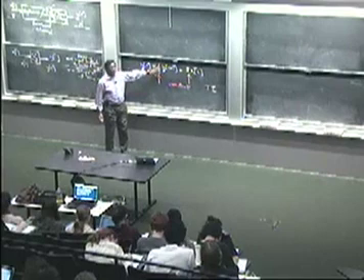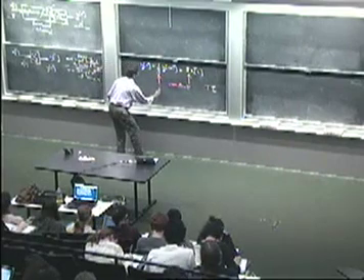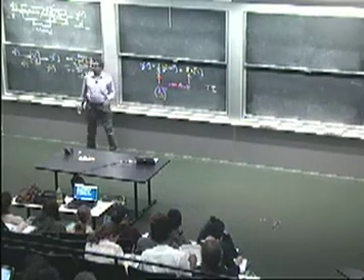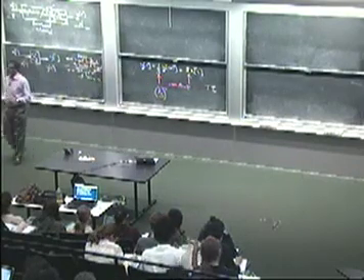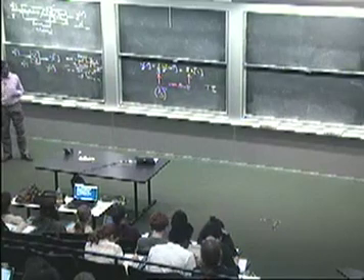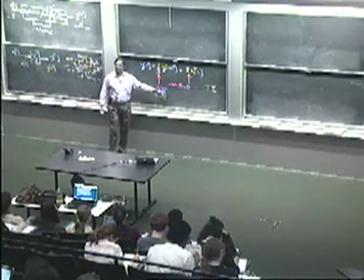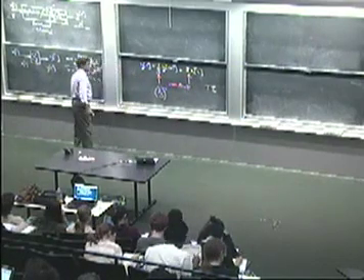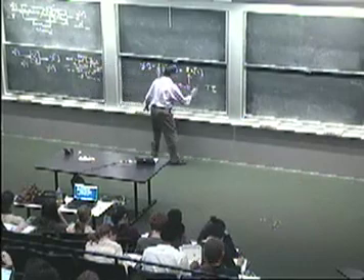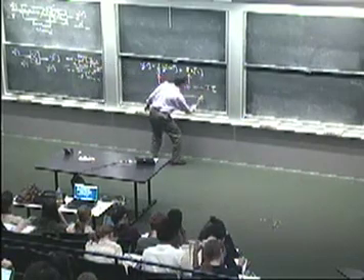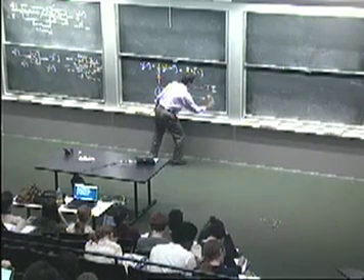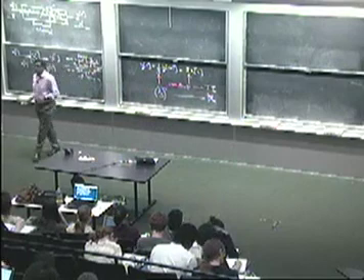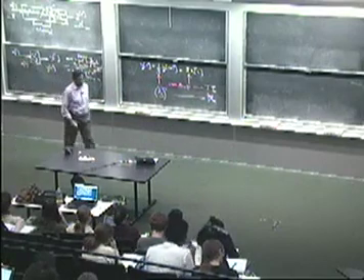But if I had here some function of n, if instead of 1/3 I had something like 1/3 to the n, now I've got a time varying system, right? Because the law by which I combine things actually depends on my position along the time axis. All right? So this would be time invariant. This would be not. So that's what this is trying to get at. Okay, easy enough.